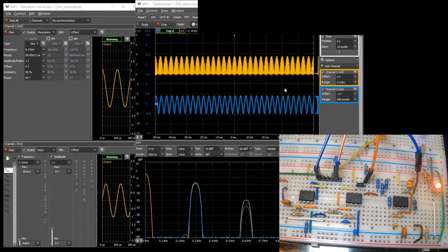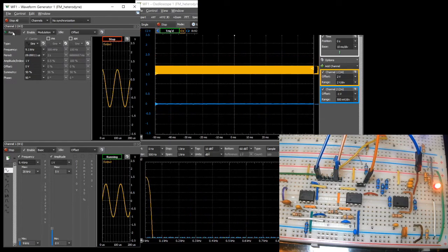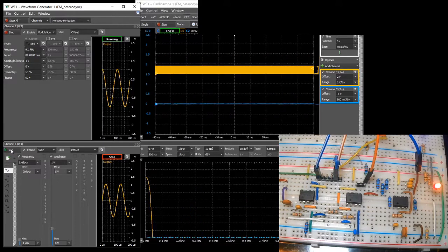The DC component is removed, and the signal now is the true heterodyne mixing component. It can be verified once more that the component requires both carriers to exist, as demonstrated, with the two carriers alternately turned on and off.